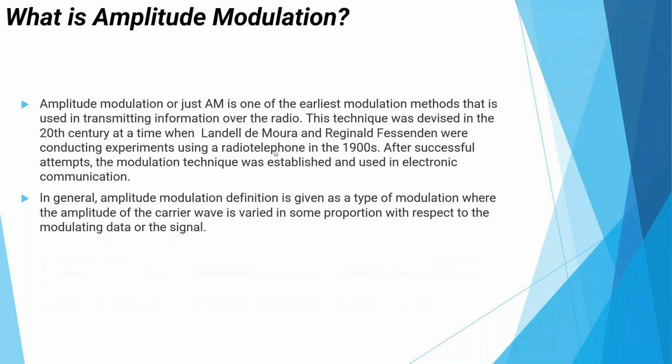It uses band-pass filters to eliminate one of the sidebands and possibly the carrier signal, which improves the ratio of message power to total transmission power and reduces power handling requirements of line repeaters. Next page.